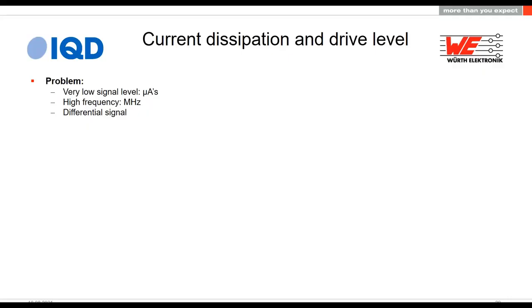The other problem that you've got is it's a differential signal, so you can't put a probe on one side that's grounded, because that ground will then just bleed away everything that's happening and the signal will disappear and it won't oscillate.